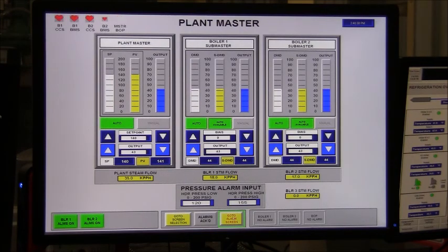That alarm should make the operator aware that he needs to look at something before you lose production due to low steam pressure, or if the pressure goes high, the boiler steam drum pressures will go high, and you may hit the high pressure cutout on the boiler, which would trip the boiler. So these should be set to some pre-warning level where the operator wants to know that he's not close to where he wants to be.